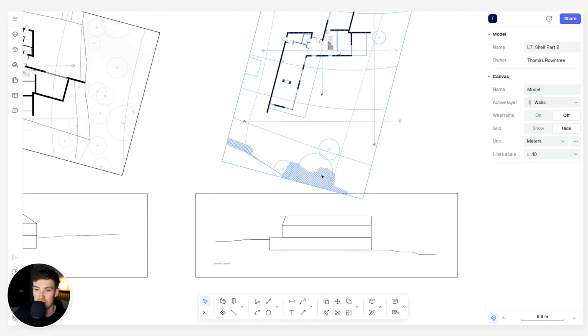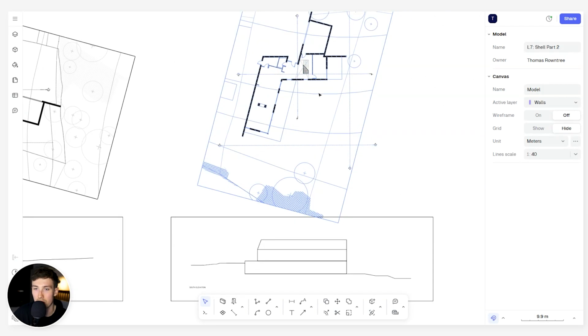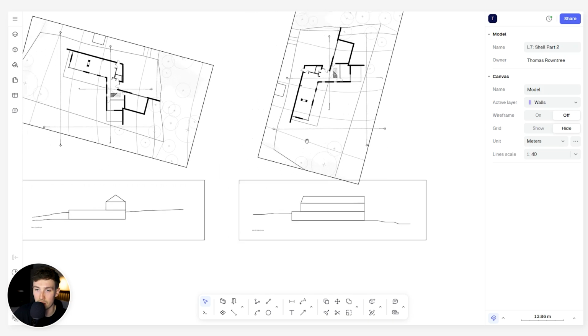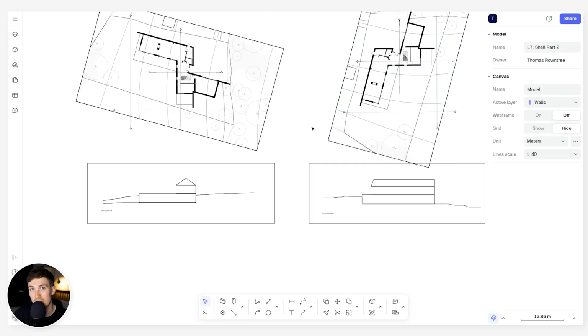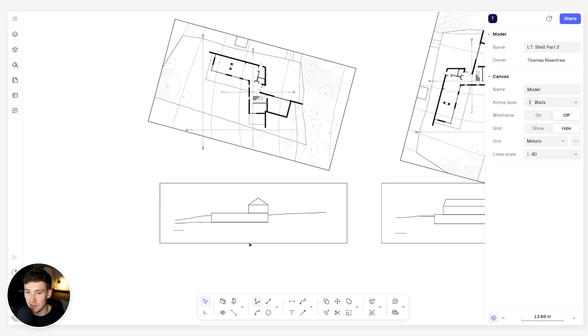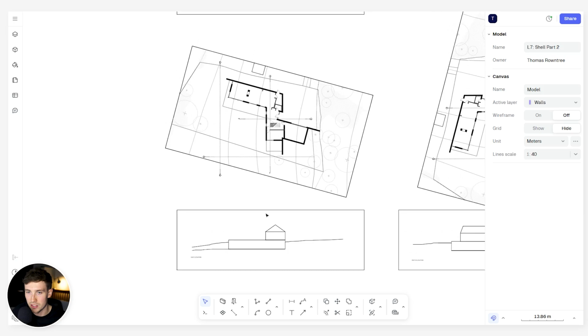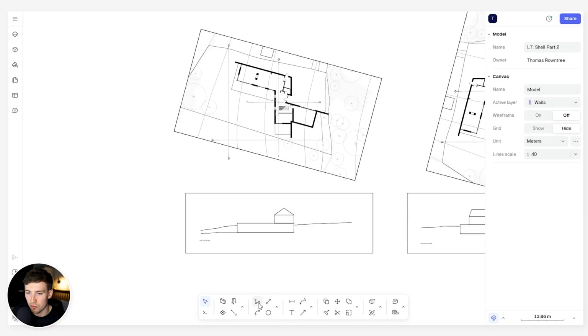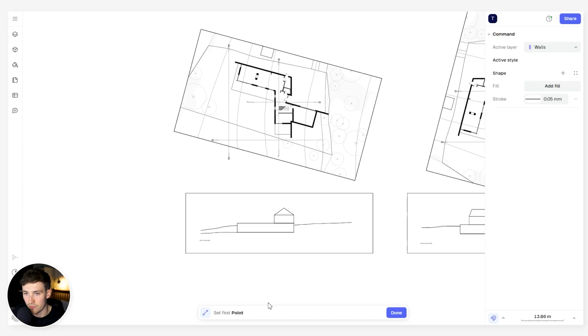And likewise with the south elevation, we can start marking up where these windows and openings are placed, and begin to work into it in elevation as well as plan. So the old school way of doing this is very simply setting up the floor plan so it's parallel to the elevation. And what we're going to do is start drawing polylines straight down from the floor plan to show the projection and the positioning of these features of the floor plan.